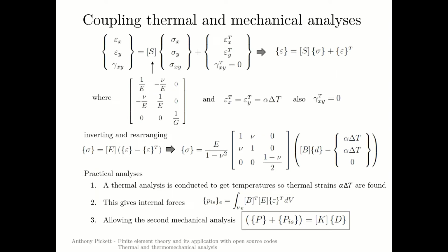First of all, this gives some brief information on coupling thermal and mechanical analyses. If you look at the top relationship here, the strains in the material are equal to the compliance matrix times the stresses that are acting, plus any strains that are imposed due to thermal effects. So this would give us our total strains.